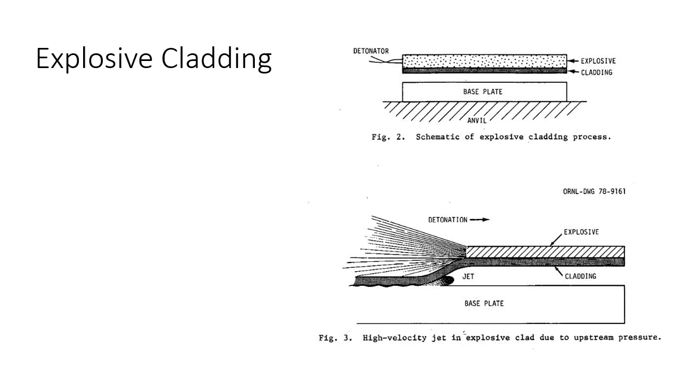There's a pretty good YouTube video on this, Dirty Jobs or How It's Made or whatever. If you do a search on YouTube for explosive cladding, it's kind of a neat one. They bury this stuff. They go in this cave in West Virginia or Pennsylvania, and they touch off this explosion, and it bonds the two materials together. They have all this explosive material on it. It's pretty cool. So, yeah, cladding isn't just putting a layer of weld material on something. It can also be, you put one sheet on and then you clad it with an explosive bond.